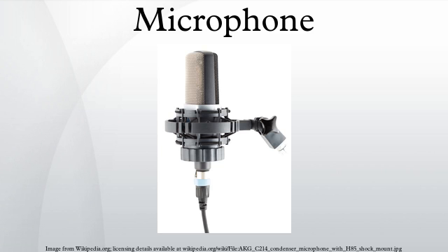Crossed figure-8, or Blumlein pair, stereo recording is gaining in popularity, and the figure-8 response of a ribbon microphone is ideal for that application. Other directional patterns are produced by enclosing one side of the ribbon in an acoustic trap or baffle, allowing sound to reach only one side. The classic RCA Type 77DX microphone has several externally adjustable positions of the internal baffle, allowing the selection of several response patterns ranging from figure-8 to unidirectional.